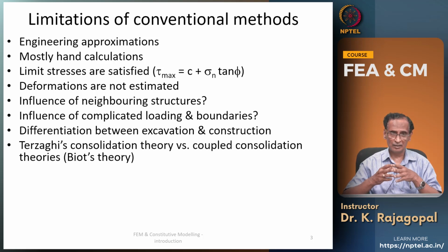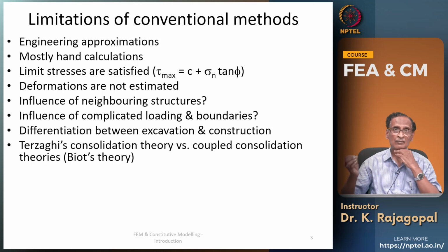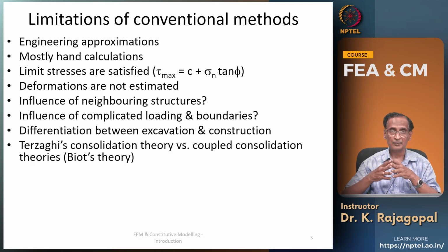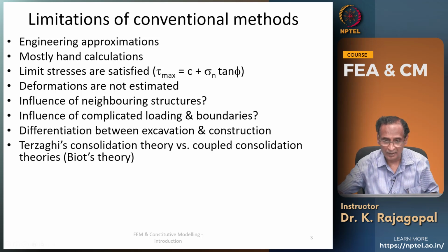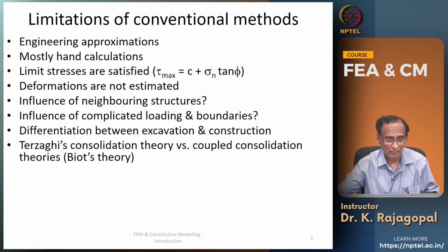Terzaghi's theory, we call it a decoupled theory, wherein we predict the pore pressures separately, and then we estimate the degree of consolidation, and then we estimate the settlement at different times based on the degree of consolidation. Later we have more rigorous coupled consolidation theories, for example by Biot.